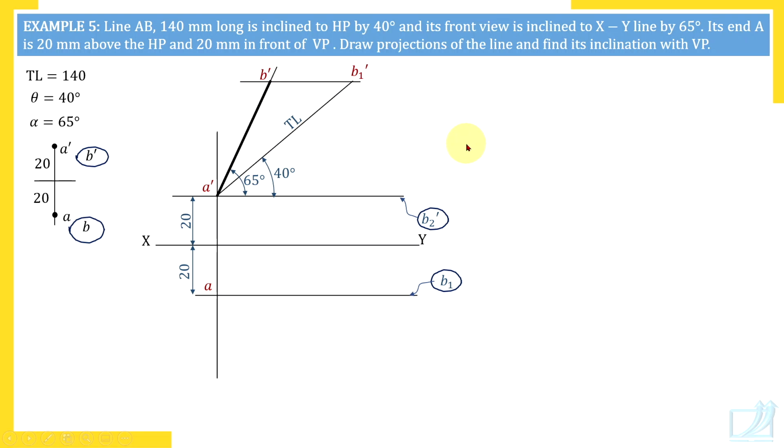Now, we will draw vertical lines. Remember, unless there are horizontal and vertical lines through all labeled points, don't use the compass. Don't rotate EL, PL. Okay. So, through B1 dash a vertical line. Which other point is on this line? B1. And this is the horizontal line on which B1 is. So, we got B1. So, remove that rough label. Now, through B dash a vertical line. Which other point is on this line? B. Remember, nowhere have we drawn any line for point B. So, just draw a long line and say that on this line point B is.